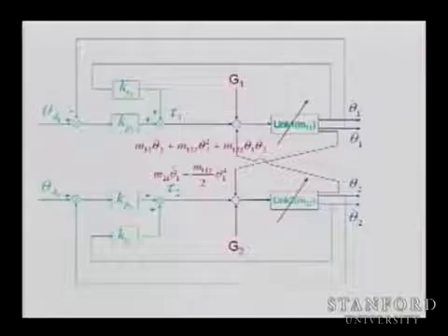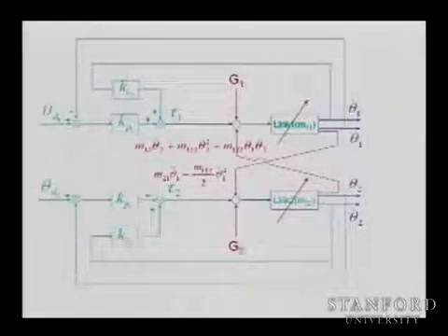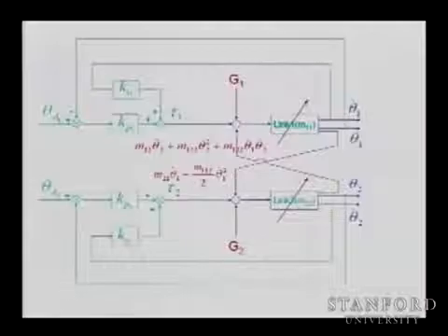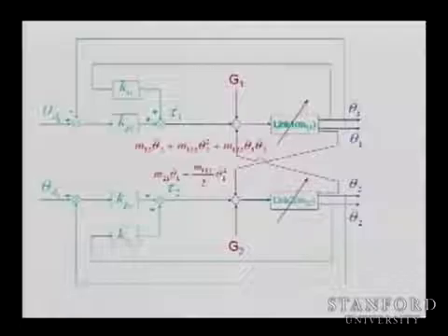So really the controller that is controlling a joint, a link, is going to receive disturbances coming from the gravity and coming from the motion of the other link. You see that? Which means that to ignore it, we need to really treat these as disturbance forces, but these are large disturbance forces.